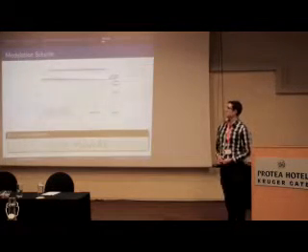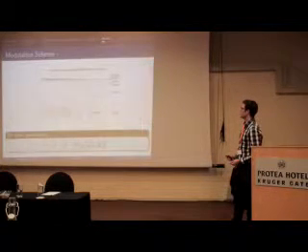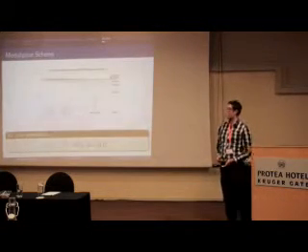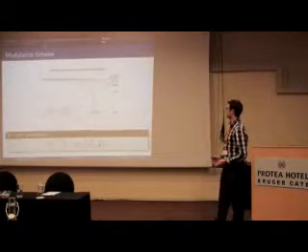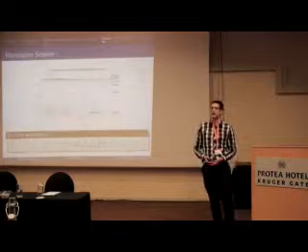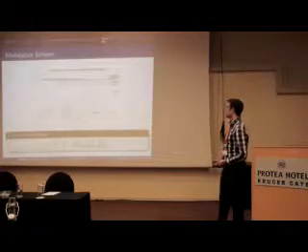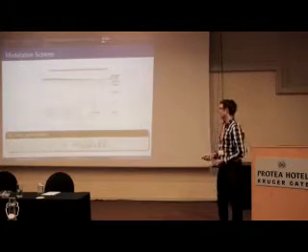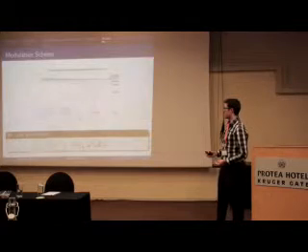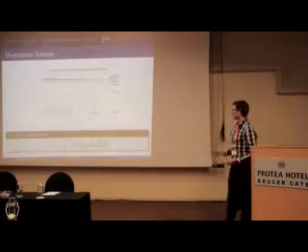So these are just some preliminary results I got. This is for the performance of selected modulation schemes. As you can see, as I increase the number of modulation symbols, I actually experience a decrease in system performance. And this is described by the second equation here, where we can see that if we increase the number of modulation symbols, which is indicated by n, it will actually increase the probability of receiving a bit error.